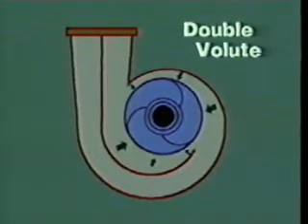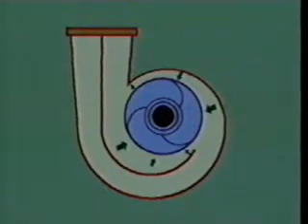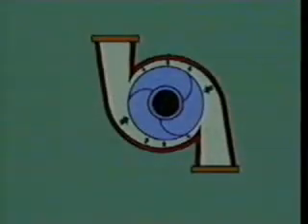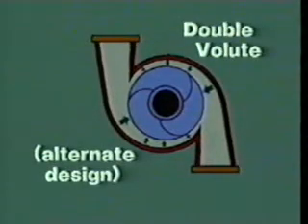The double volute casing provides a second guiding vane to split and balance the internal radial forces. There are other advantages of double volute casings. They give the casing greater internal strength. They also reduce some of the stress load on the casing walls.